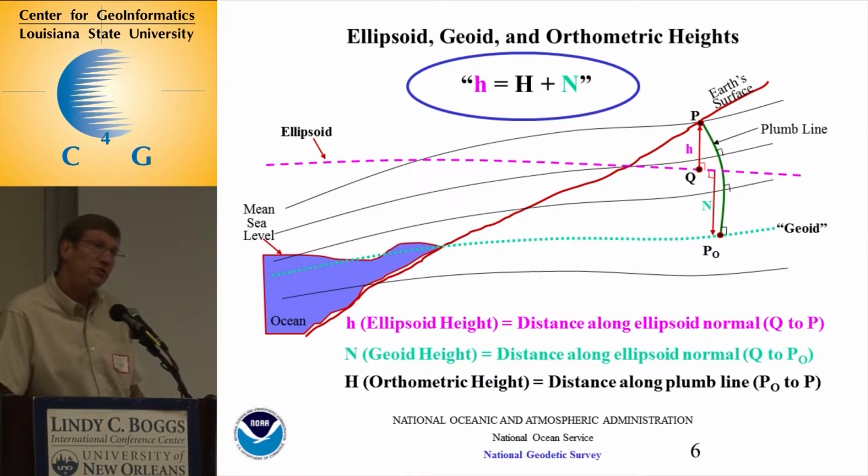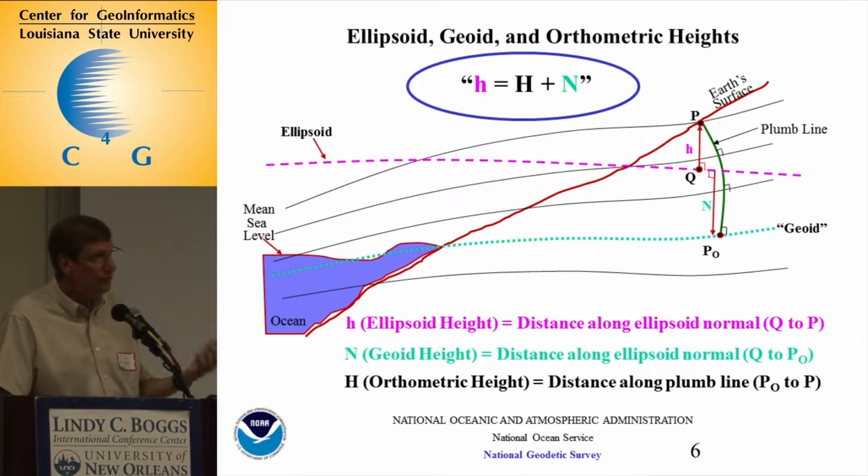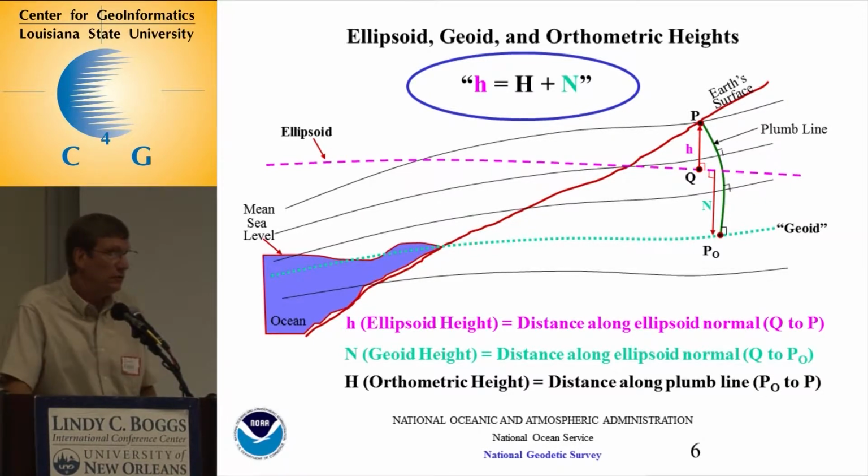Now, in our procedures for the orthometric height, you'll see later on this afternoon, even if you have slightly different geoid models, if you follow the procedures, then you would still end up with NAVD88 heights that were pretty consistent, and then that geoid difference might drop out on your local project. But you still have to be careful. You could compare GPS-derived NAVD88 heights, the final product, with each other, if you follow the appropriate procedures. But still, the geoid model could make a difference in some areas.